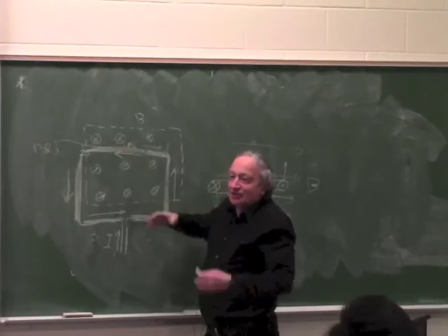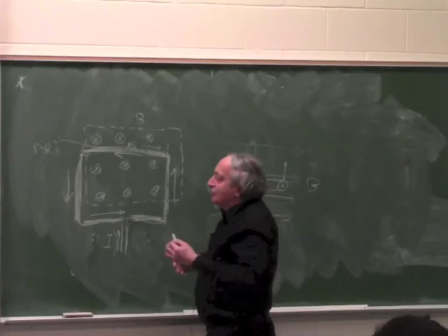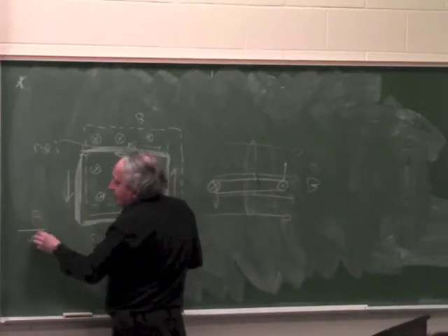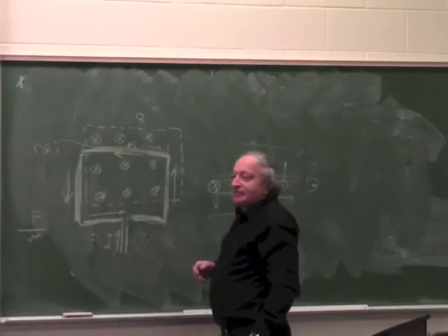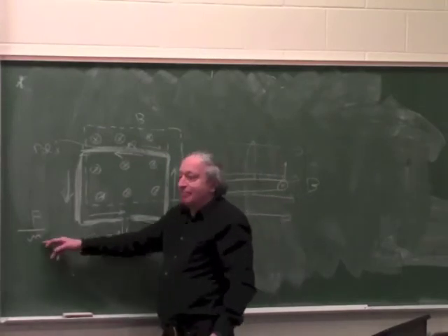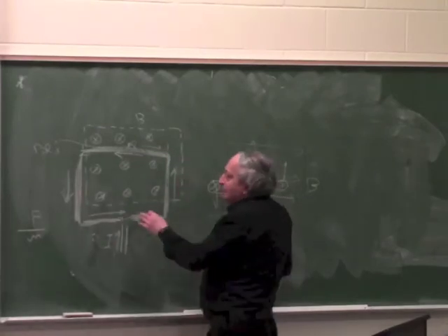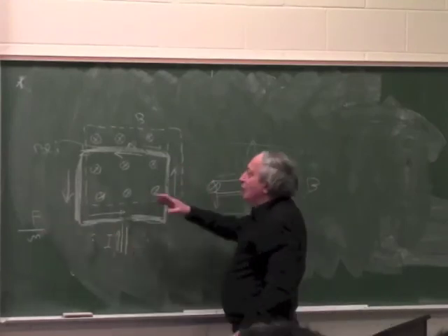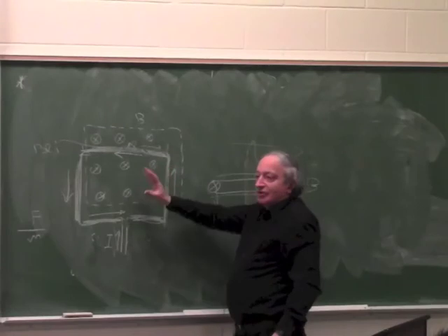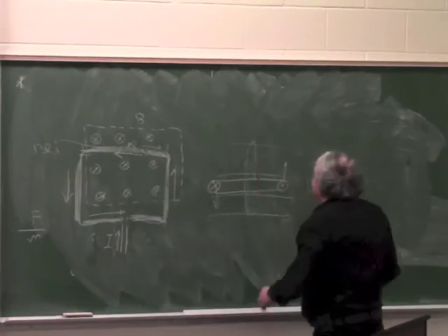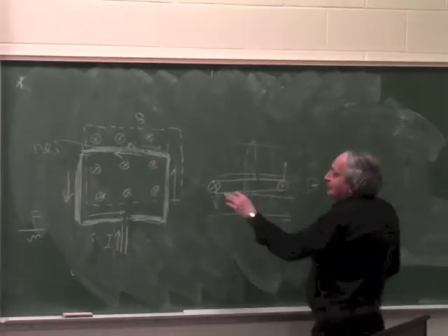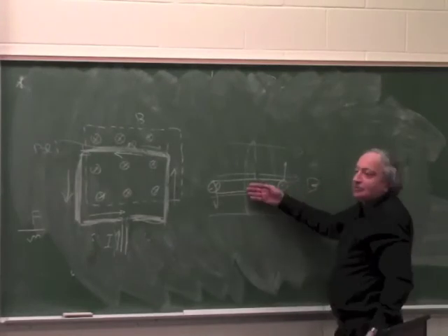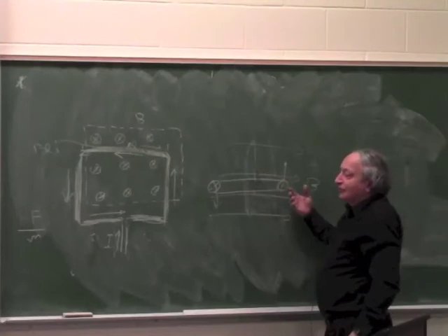So if you think of the efficiency of the actuator, which is the force over the weight, the M is a mass. So this has 4 masses, but only 1 force. Now, if you want to make a coil which generates a torque, the situation is a little bit better, because in this coil, which is wound this way, 2 of the arms generate torque and the other 2 do nothing, but at least 2 of the 4.